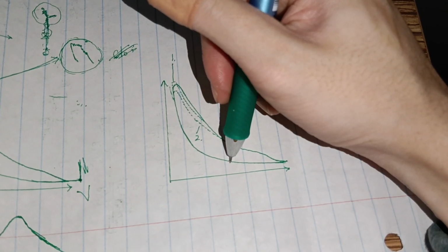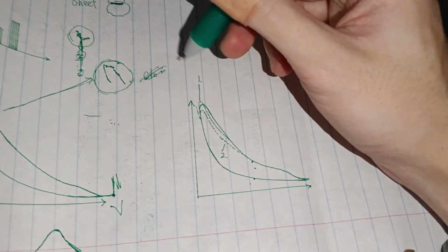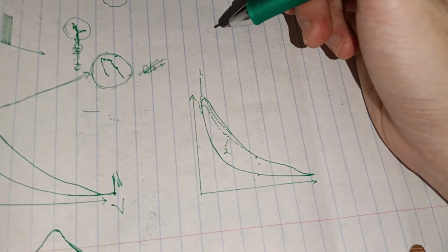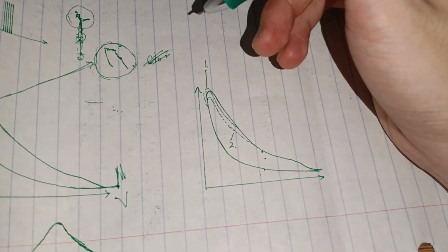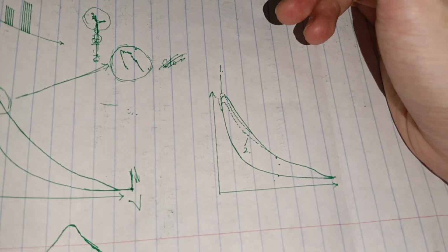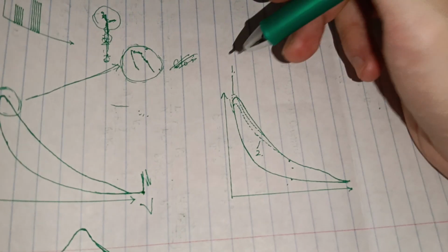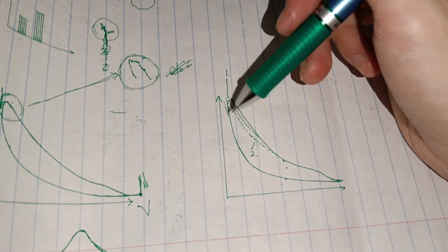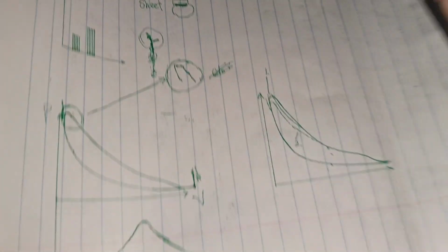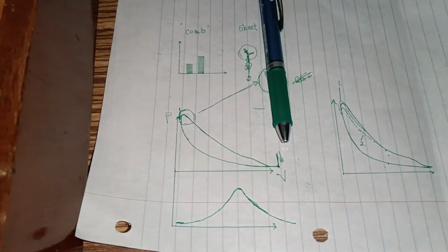Sometimes if both of the compression lines are lower than usual, this actually means you have a leaking combustion chamber, like the piston ring or the piston head. In that condition, you will notice a significant amount of oil mist in the crank, like the scavenging space.